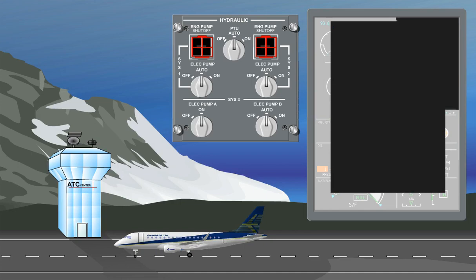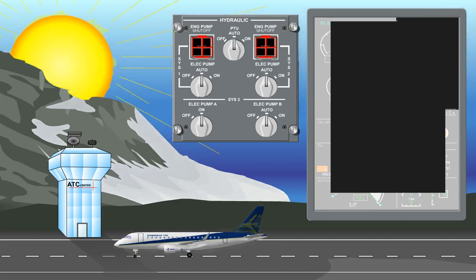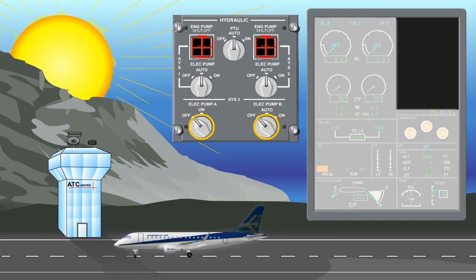During normal operation, the hydraulic system will operate at a temperature comfortably below the high temp caution threshold and considerably below the overheat warning threshold, the only exception being on-ground operation on an extremely hot day, where System 3 fluid temperature may reach the high temp threshold and cause the ICUS message to be displayed. Switching System 3 off while the aircraft is on the ground and switching it on again for flight operations can counteract this.